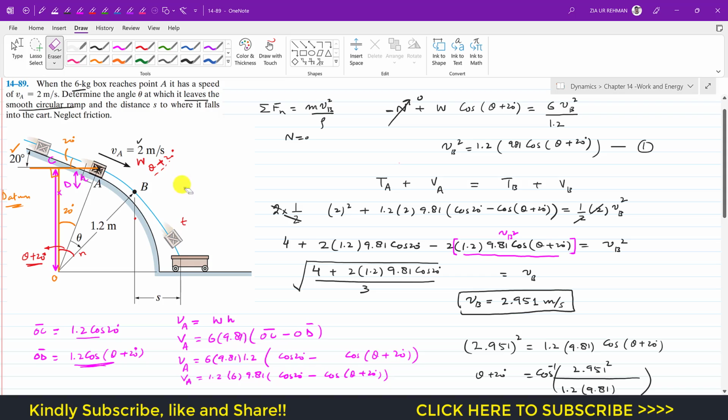For that, after point B, when it loses contact with the ramp, it follows projectile motion. For projectile motion, let's say that our coordinate system is located at point B. This will be the initial position of the projectile, this is the x direction and this is the y direction.